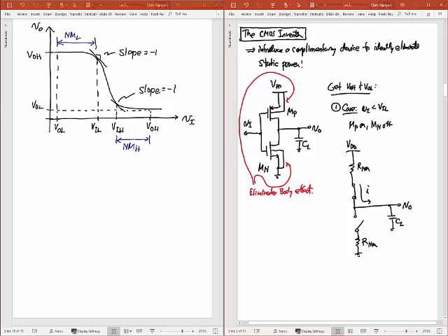And as it goes to C sub L, that means this thing, which represents the PMOS transistor, the PMOS charges this node all the way up to this voltage VDD. It's basically putting positive charge on this side of the capacitor. Naturally, the ground part will be the negative charge on that capacitor because you have to have equal and opposite charges there. But I could say basically that the output high voltage is just going to be VDD in steady state.